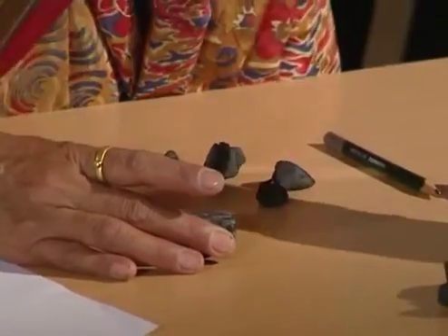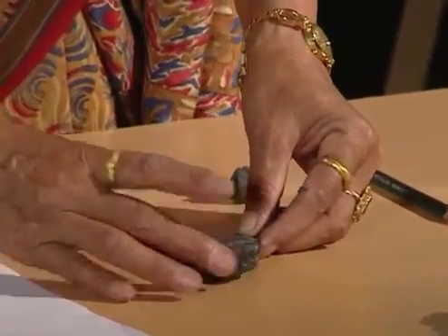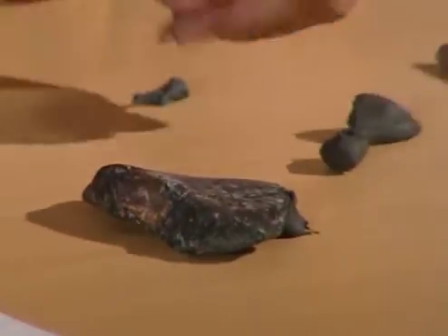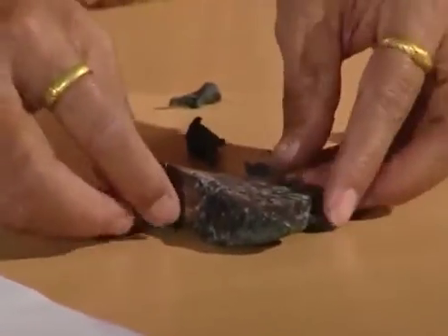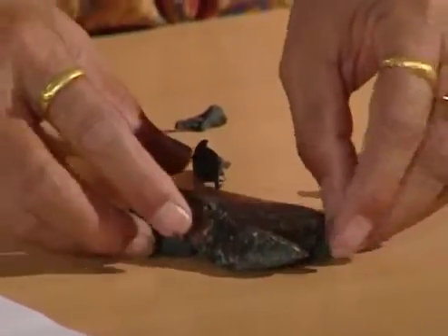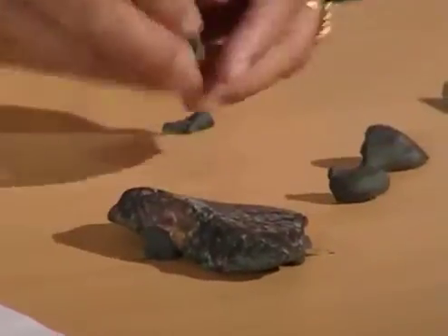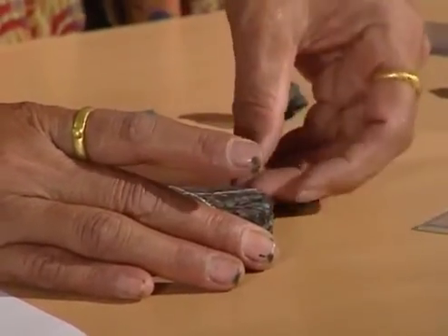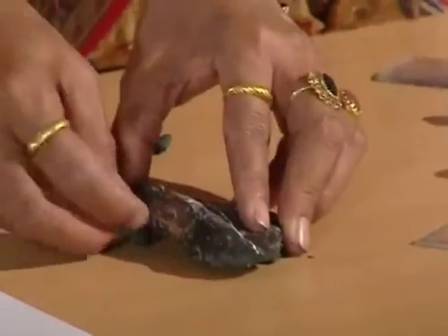If 3 points out of these 4 end points get similar height, considering the nature of workmanship, it should be considered that the specimen is placed and fixed properly. Otherwise, the position of the artifact should be changed, and the same procedure should be repeated until the specimen is placed and fixed properly. Number 6. If the artifact is placed properly, the next step is fixing the specimen in its proper position by filling the gap using plastic sheet.